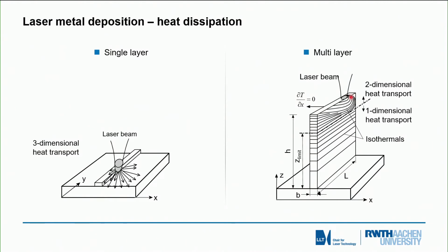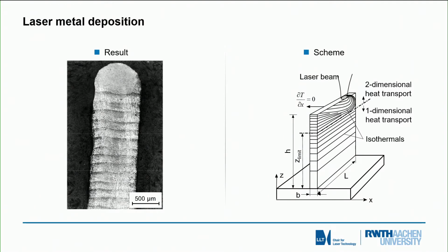There will be heat accumulation at the edges, which we can take care of by reducing the laser power or increasing the speed.